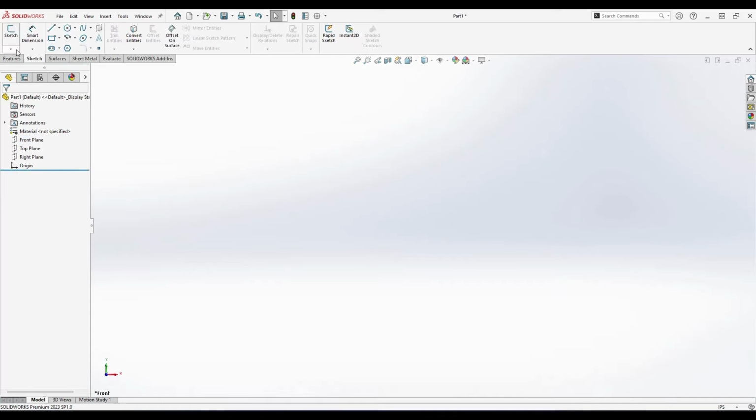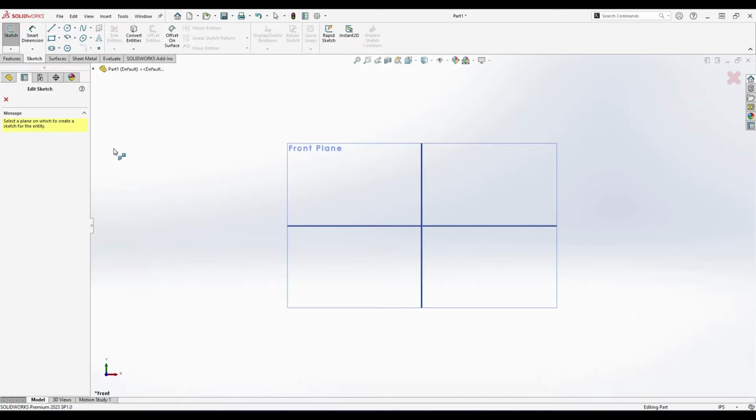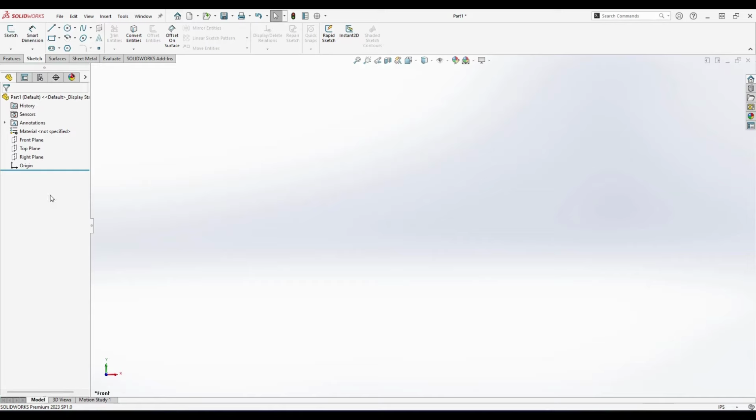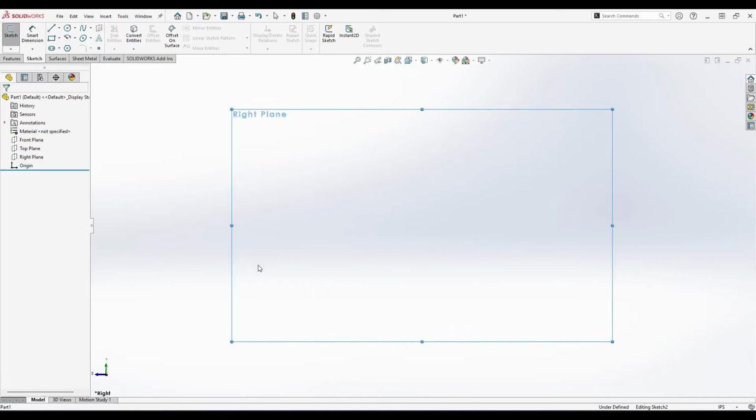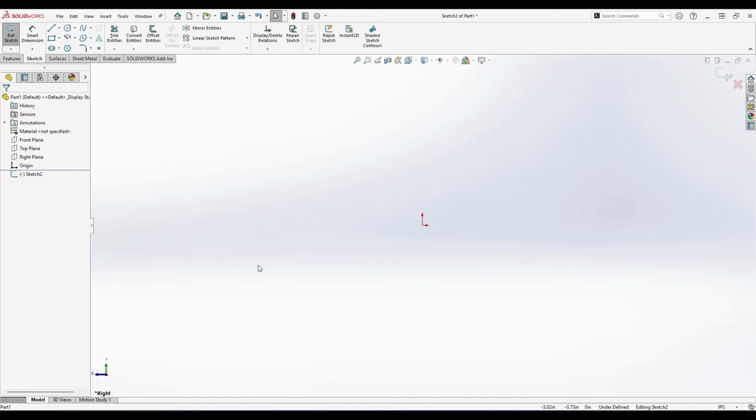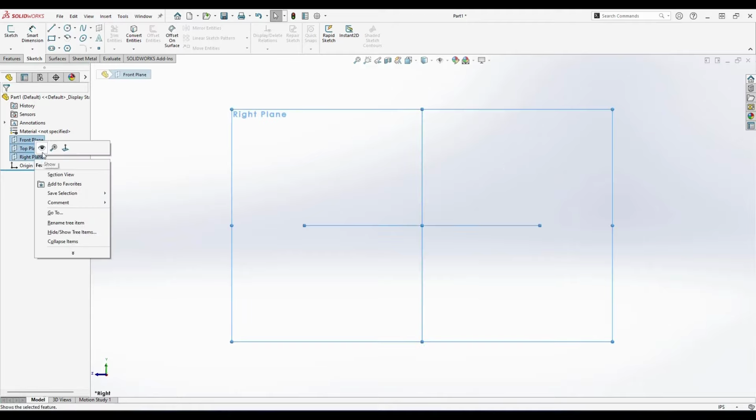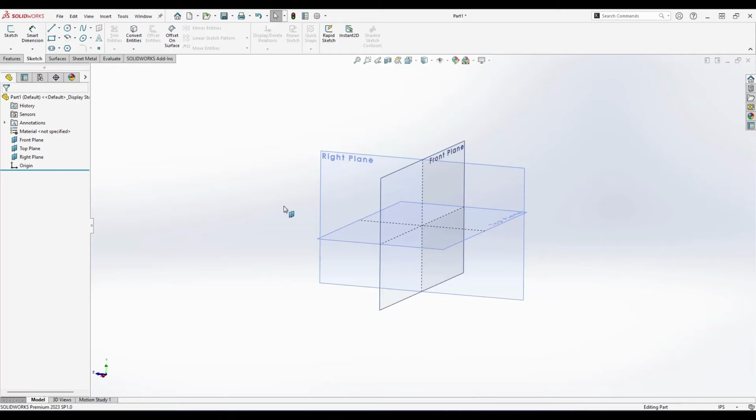The other way is you can go to the Sketch command first. So what I'm going to do is go to the Sketch command first, and I'm going to select a plane later. So this is another way of entering into a sketcher environment. And there are many other ways. Suppose these planes are switched on, and you can see here there are many planes.